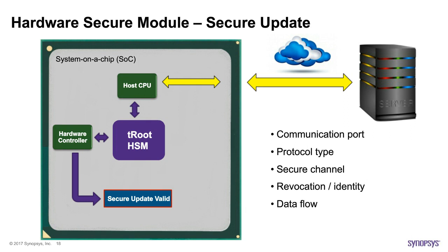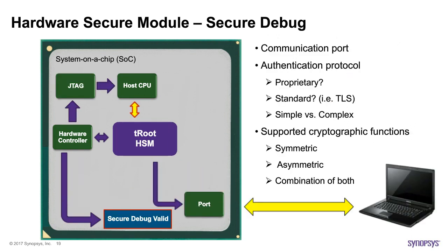The last feature that I want to talk to you about today is secure debug. Its purpose is to put the SoC in a debug state, a vulnerable state for anyone wanting to control and/or acquire the information from the SoC. Therefore, it's important to enable this state in a secure way.